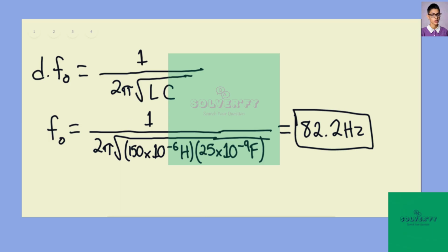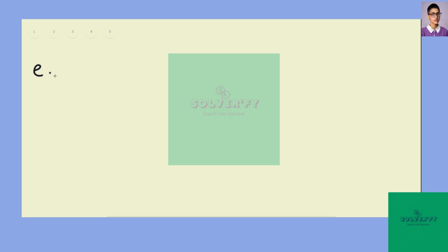And then we can say for part E, at the resonance where the inductive reactance equals X sub C, we can say that then the value of Z is equal to the resistance, that is R. My apologies, this would be X sub C. So when the inductive reactance is equaling the capacitive reactance, therefore the impedance is simply equal to the resistance that